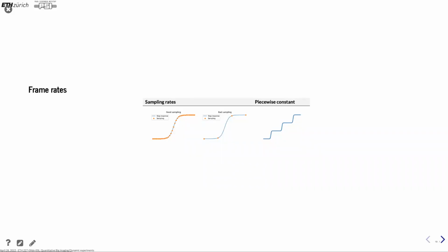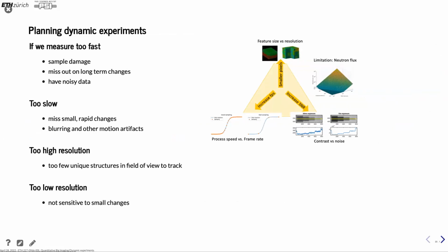Then when you're done, you go to the next level, let that go to steady state, and so you take out all the transient effects. That requires, of course, that you can control your process to that level. It's not always possible, and then you really have to go towards increasing the sampling rate. So as a summary, we have the planning of dynamic experiments.